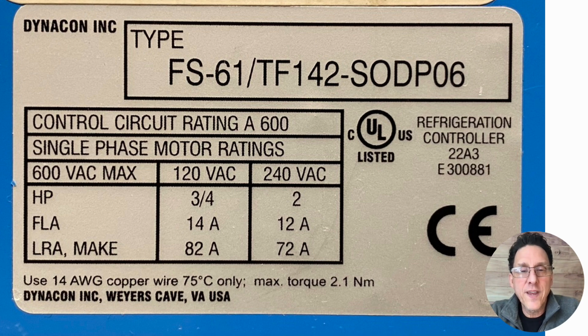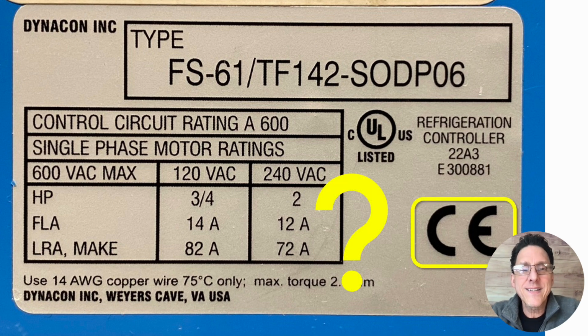Okay, and one more thing I want to talk about here. What's this mark right there? What does that CE mark mean, right? That has nothing to do with a testing lab, right? That is not a safety certification. It does not demonstrate compliance to North American safety standards or any installation code. That CE mark is required on products in European countries that are part of the European Economic Area, the EEA, to facilitate trade between those member countries. That's all it is. It has nothing to do with electrical safety. It's just to allow free trade between those European countries. That's it. It's not CE listed, in other words.